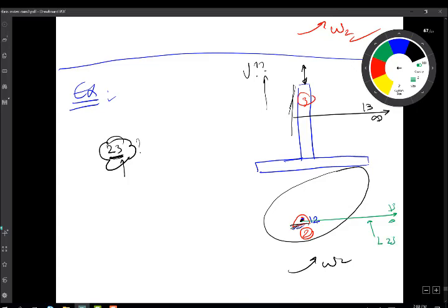So that's a locus. I need another locus for 2, 3, and I'll get it from the contact between 3 and 2. Now, don't forget, this contact is not a rolling contact in any way. So the point of contact is not the point of common velocity. And that's a mistake, students. You do that, that's a big problem.